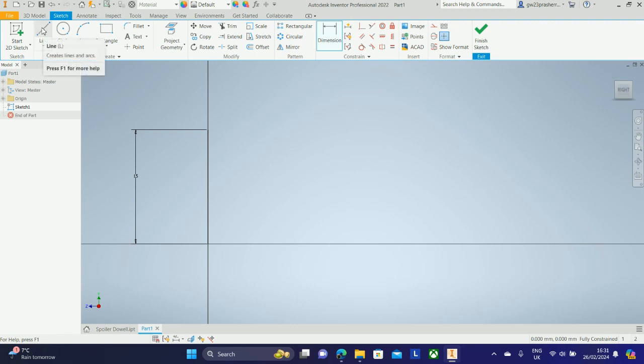I'm then going to select the line tool again and click the green dot at the bottom of our 15, where the axes all meet. And I'm going to go out to the right hand side at 90 degrees and I'm going to go out 20. So again, select a line, press dimension, click the line, click off it and make it 20. This now gives me 2 points to start an arc. So I've got the top point in my 15 and I've got this side of my 20.